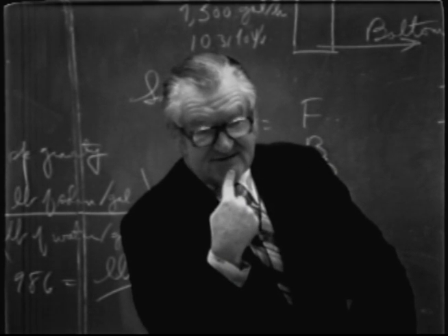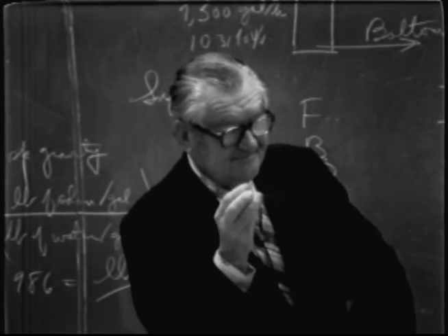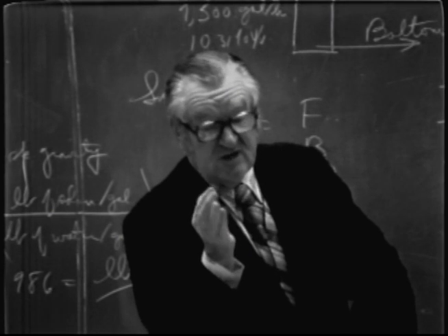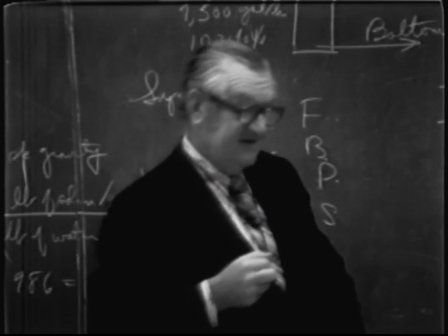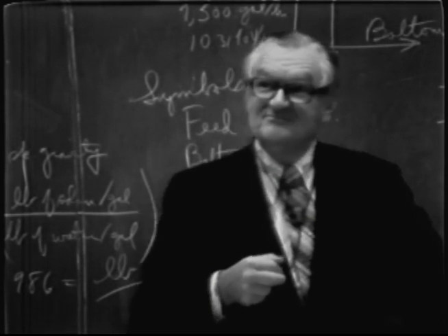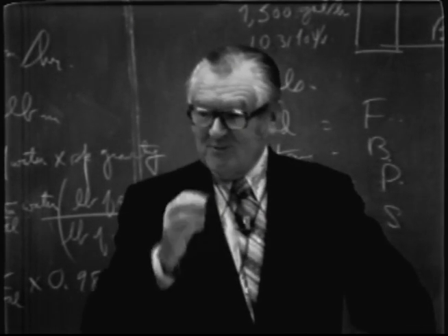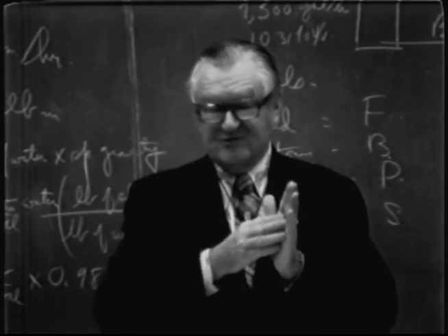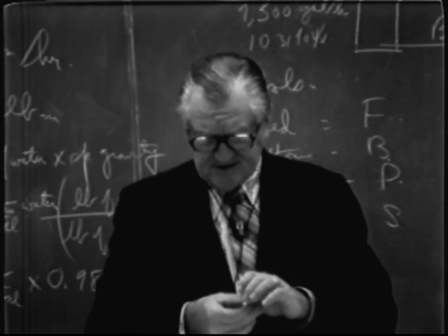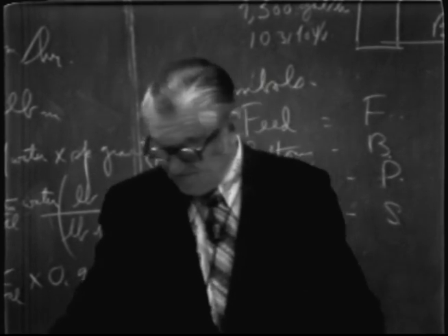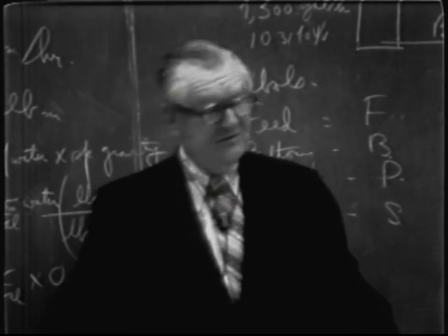It's sufficiently constant, or independent of composition, that we can assume we have what we call a constant molal heat of vaporization, or the heat of vaporization on a mole basis is essentially, I forgot what the figure is, about 33,000 BTUs per pound mole. And it doesn't vary more than about 1 or 2% over the whole range from 0 to 100% alcohol. So it's a simplification that enables us to solve problems that otherwise would involve complicated energy balances.